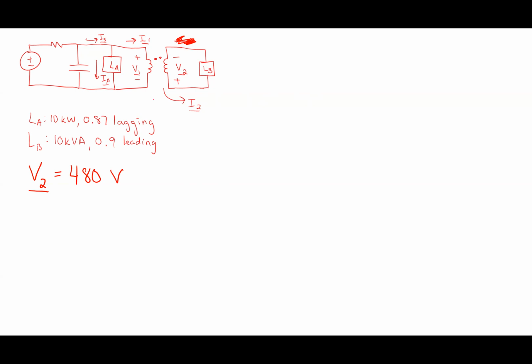I didn't write a lot of stuff. 8-to-1 is the transformer turns ratio. That doesn't mean 8 turns on the primary. That means 8 times the turns on the primary. You wouldn't have a one-turn transformer typically. I would say start at the load and determine the real power. Yeah, exactly. We'll start there when we start doing all the calculations for sure.